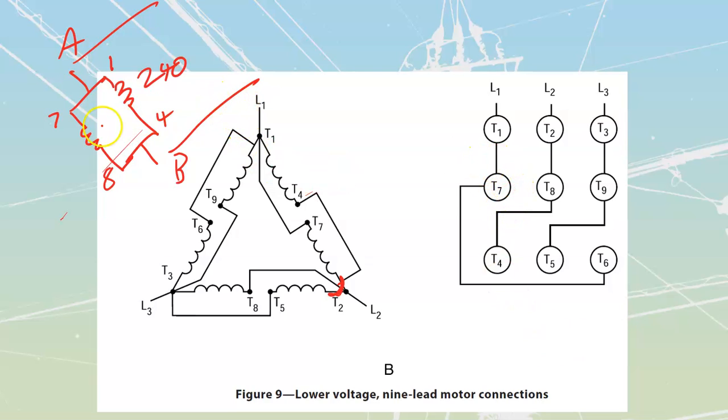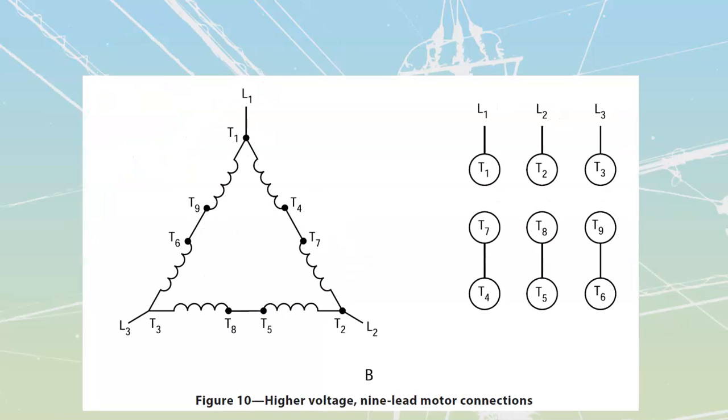If I wanted, I could take the same 9-lead and I could just series them out over here. Remember that my 1 is connected already internally across to the number 10 over there, so we don't see those number 10s off of these ones. But I'm just going to make this series connection now across here, here, here, and here. Same components, I'm just now series connecting them across over here.